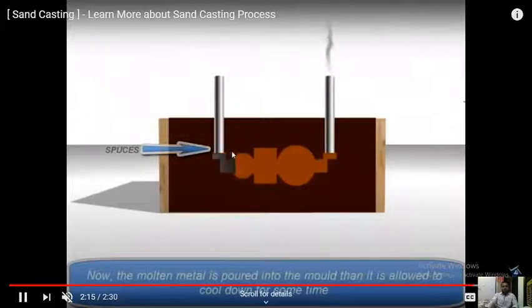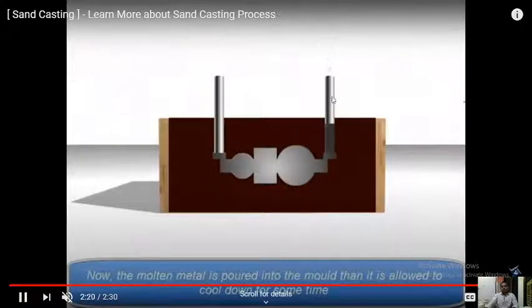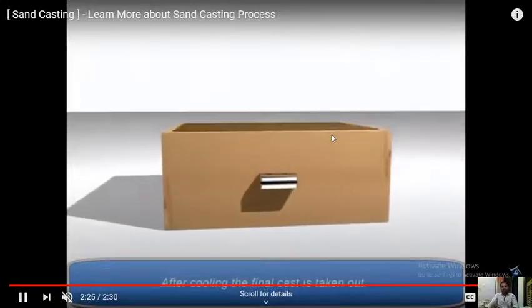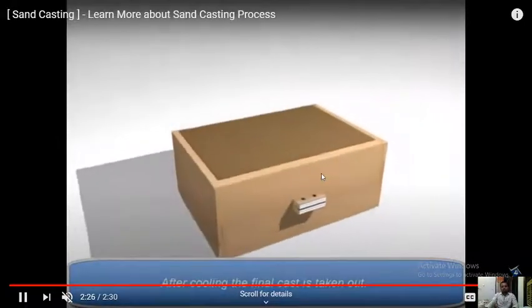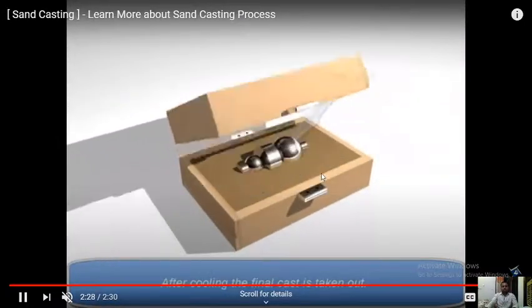And then you will see that molten metal you can see is filling from it, and this will be filled in the riser. And when there will be solidification, you just see the height of the molten metal is just lowered because it has just compensated the contraction.